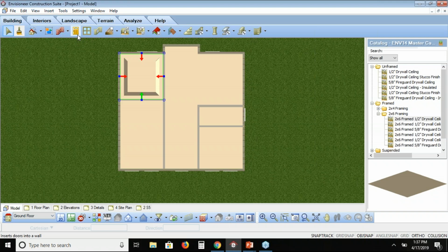But when you do need to customize, as we've shown you, you can go in and change everything as you need to if something doesn't follow the rules, or you need to tweak a formula because you want to add in a bigger waste factor on that drywall, you can do so. So this little ceiling here is now trayed.